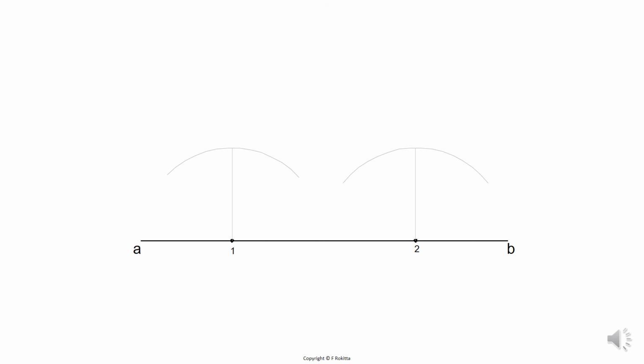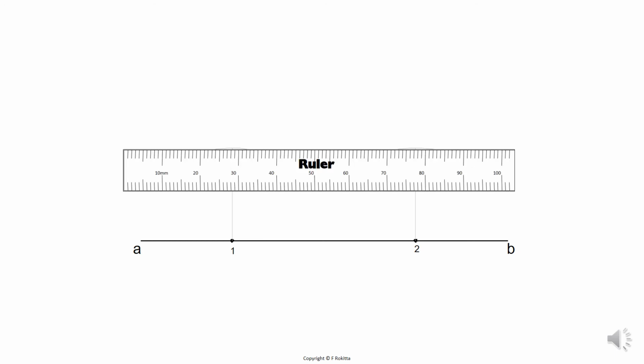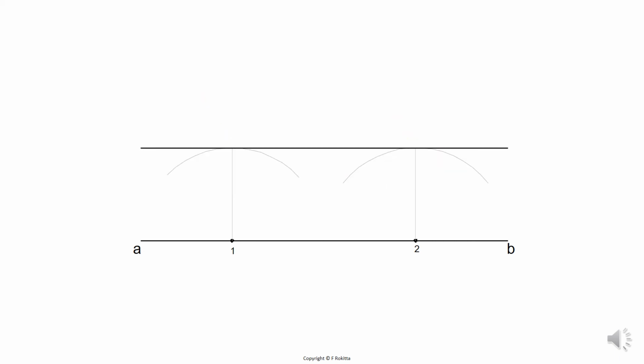Next, you need to take your ruler, make sure that it is still perfectly parallel to line AB and that the edge of your ruler actually meets with the touch points at the pinnacle of the arcs at number 1 and 2 and where the vertical construction lines meet with those arcs, and draw a solid line through those intersections. And this will create your parallel line. This line will then be perfectly parallel to line AB. And lastly, we will label the parallel line as line CD.